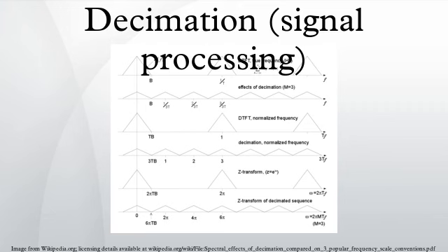For completeness, we now mention that a possible, but unlikely, implementation of each phase is to replace the coefficients of the other phases with zeros in a copy of the h array, process the original x sequence at the input rate, and decimate the output by a factor of M. The equivalence of this inefficient method and the implementation described above is known as the first noble identity.